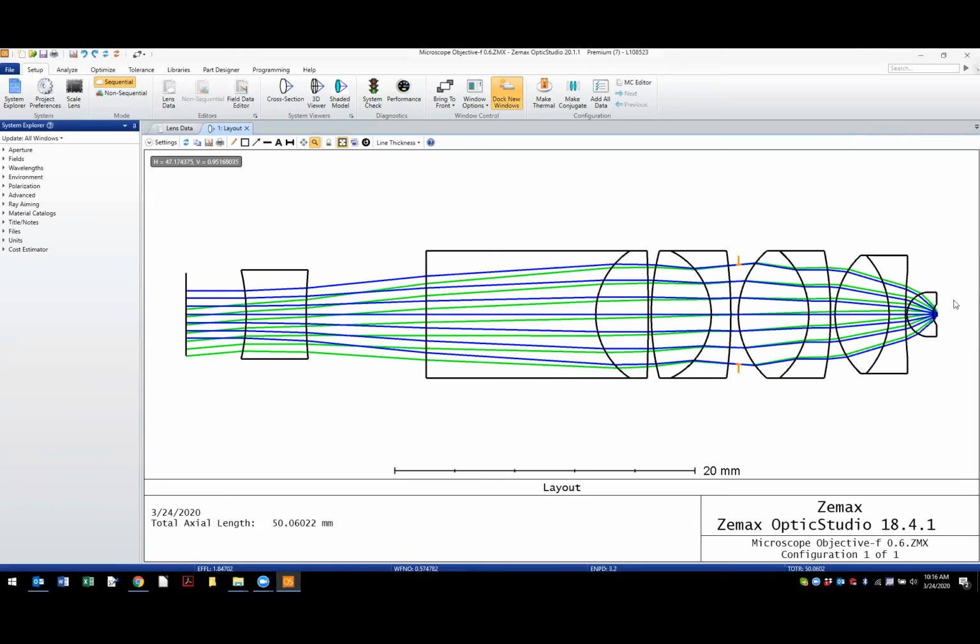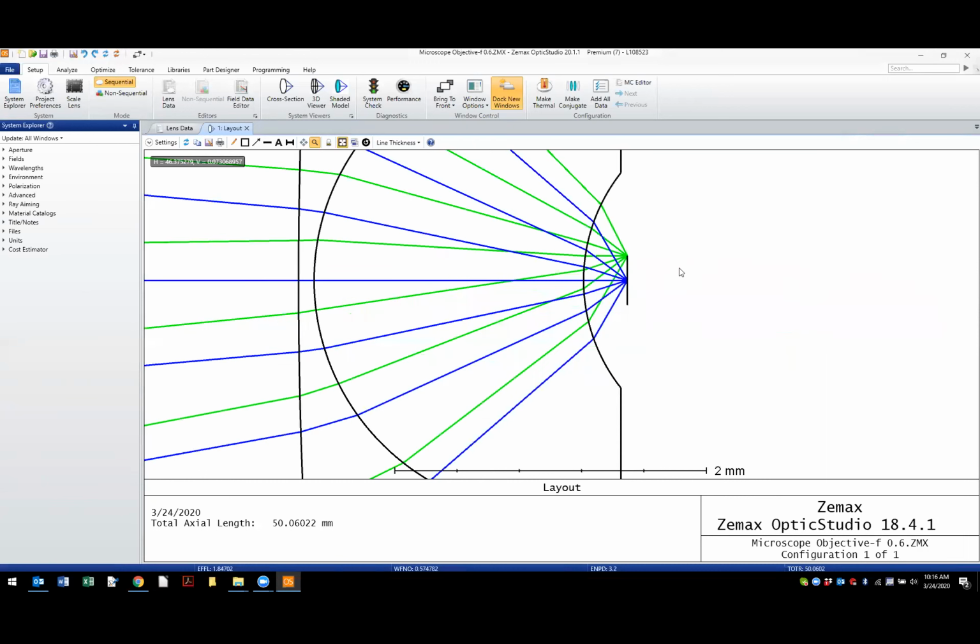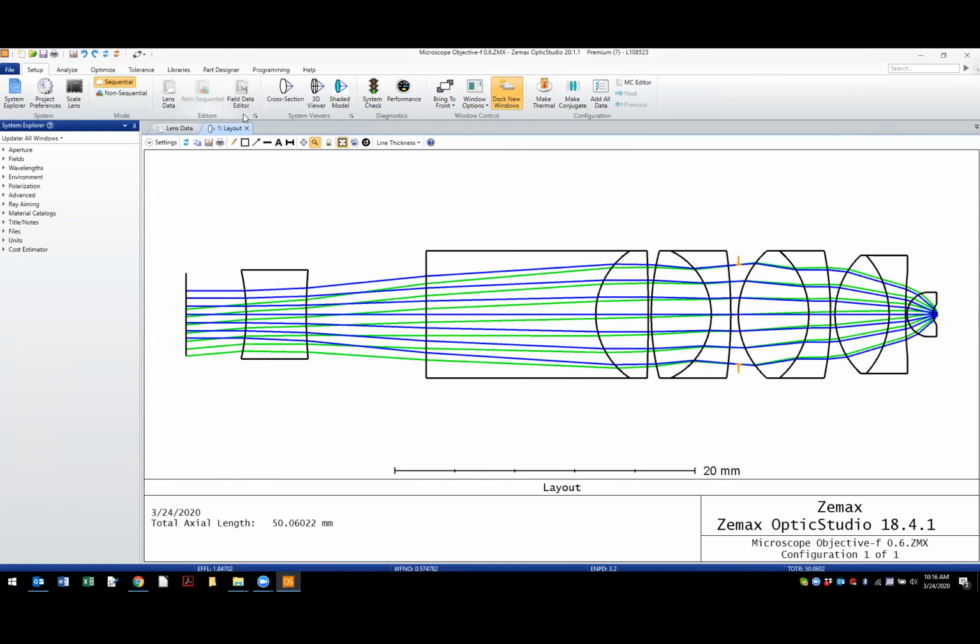There's a few reasons why people do that in Zemax. For one, doing quick focus so that it automatically adjusts the last layer thickness, the distance from the very last lens to where the image forms. That's easier than doing quick adjust. So it's just to make things a little bit lazy for the user.